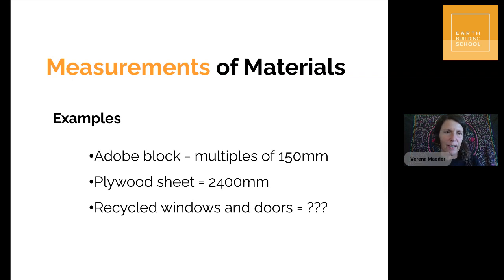The other thing that you could take into account is the size of plywood sheets. As I said, they're quite commonly used either in flooring or in the ceiling. And the size of a plywood sheet is 1.2 meters by 2.4 here in Aotearoa, New Zealand. Maybe it's different in other places. Research it and try to incorporate this if you're going to use it, so that you have only part sheets. You don't have a little bit more than, let's say, 4 sheets or something like that, and you actually make economic use of your plywood.